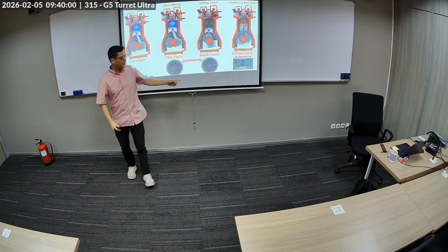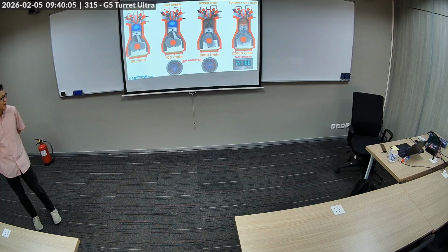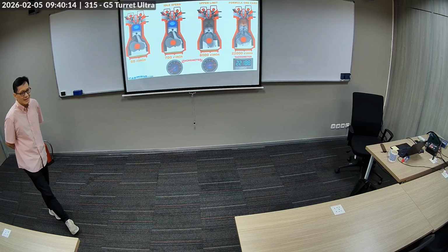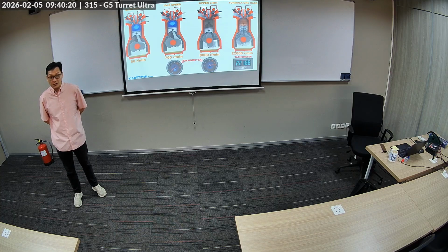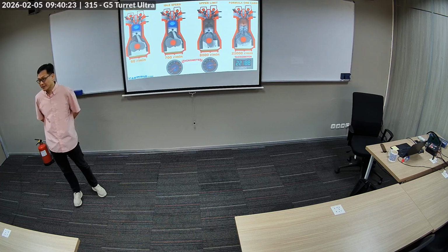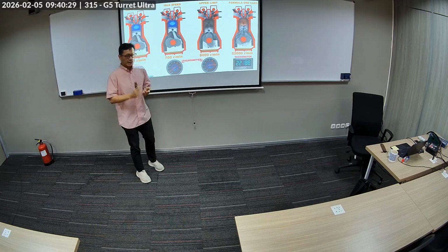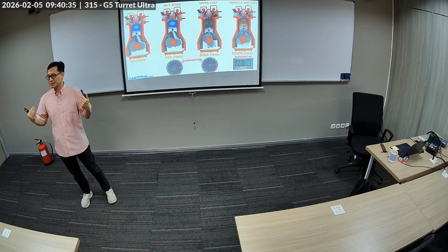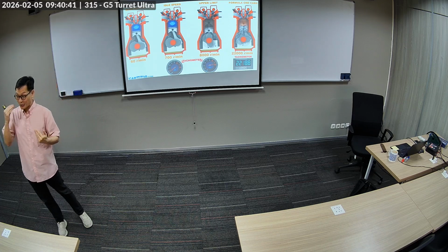That's typical. That's already pretty high. I mean, some economy cars probably have like 6,500 or so. My Integra has 8,000 as the RPM limit. The bigger the displacement, the lower the red line tends to be, just because you have more mass moving. So V6 and V8 engines will have lower red lines, just naturally because of too much mass, right? Remember, red line is all about lightweight and less inertia, less acceleration, because F equals M times A. So either you have lighter mass or lower acceleration.